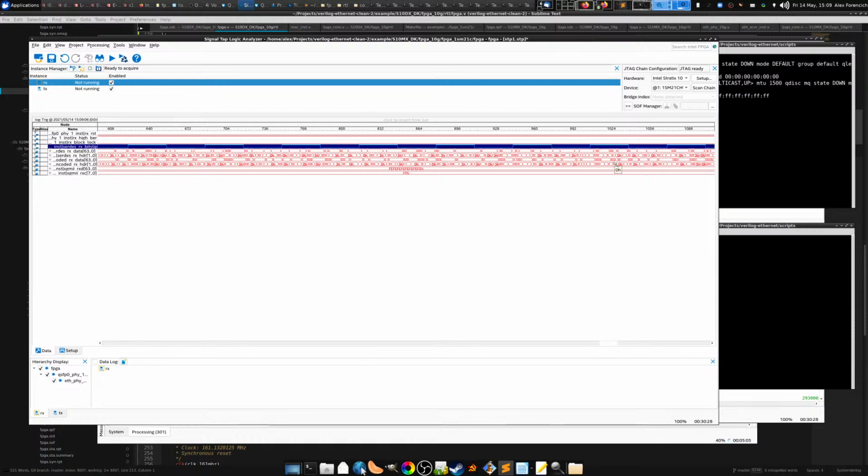So that means that the PHY is trying to lock, and it keeps slipping to a different bit position in the serializer, but it can't find the pattern that it's looking for. We'll take a look at the Ethernet specification, and I'll explain how the locking works in a minute. But let me switch this over to a different NIC. Hopefully, it'll be able to lock.